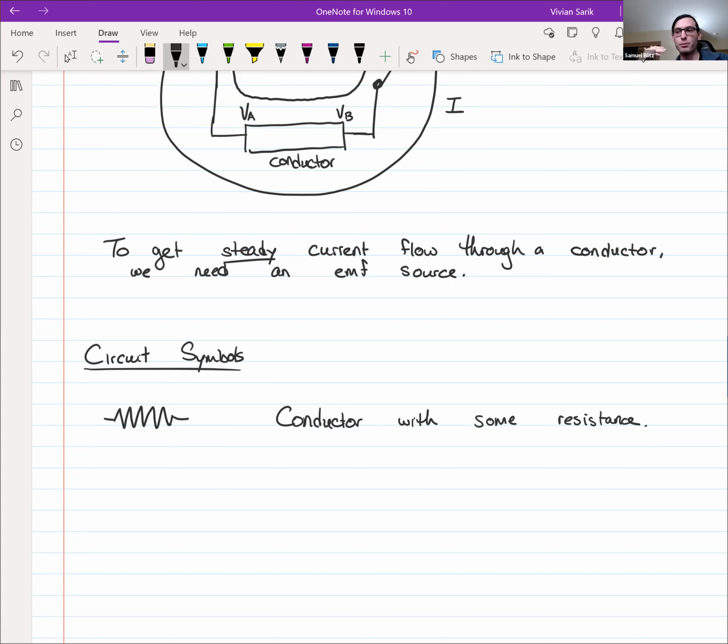And so you might describe a 10-foot long piece of copper wire as a really long equipotential and then a little 2 ohm resistor at the end. That would be the same as if you had a bunch of little baby resistances the whole way, and we'll get to why that's the case. But we do that often. So often if the resistance of a real life wire is relevant, we will separate it into 2 parts. There's the equipotential aspect and there's the resistive aspect, and we just put them next to each other.